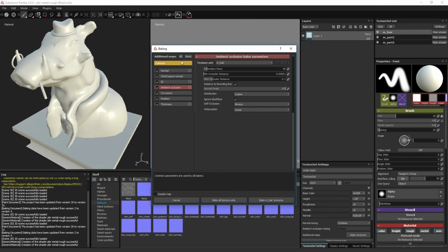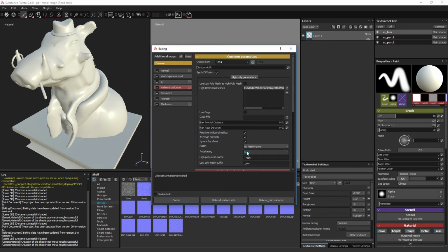The anti-aliasing method increases the number of texels in the UV range by a set multiplication to further refine the detail during the baking process. It then finds the average color shared between these smaller points and uses it to color the actual pixel. This lessens the zigzaggy look between high color contrast pixels, as they instead use the middle ground within the area. Increasing the anti-aliasing factor will increase the time for the baking procedure.